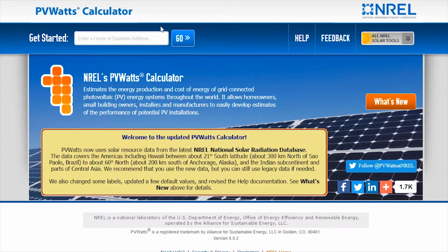In this video we are going to talk about system performance, and that's an important topic because performance drives the economics of a solar project. So the first step in the process, in the design phase, is to come up with a projected production. A simple way to do this is to use the Department of Energy's PV Watts calculator.